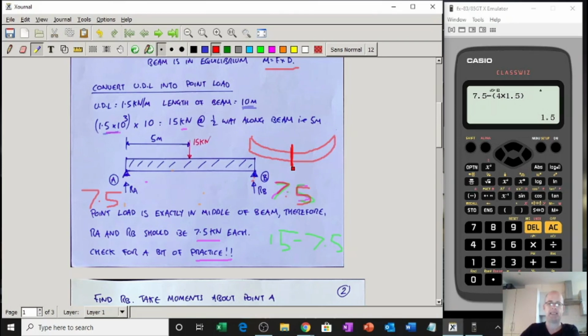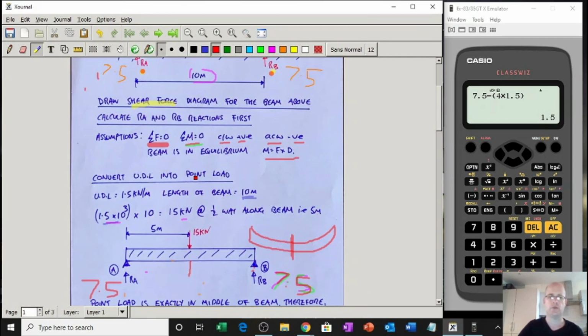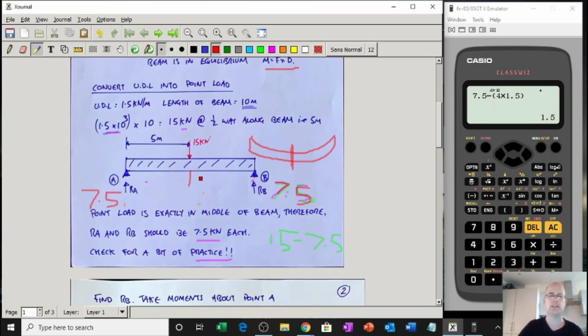And the maximum bending moment is going to be in the middle, which is going to be x equals 5. So I want to see what the shear force there is, because when there's maximum bending moment, there's 0 shear force. So I know that at x equals 5, I'm going to get the maximum bending. Normally, you'd have to trust the shear force diagram to find that. So if you went to x equals 6, you'd miss that point.